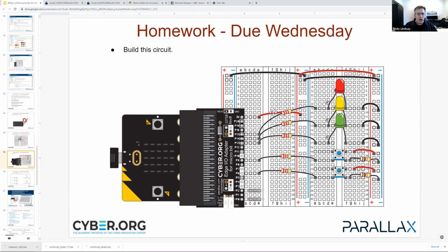Are there any questions while we wrap it up? And also, would anybody like some additional support? For example, any of you who have tenuous voltage readings, if it was flickering between 3 volts and some lower value, we may want to take a closer look at that. If you could email me, we can set up a time to quickly meet over Zoom and look at your board and your alligator clips, and possibly swap out with different alligator clips and see if the problem goes away, things like that.